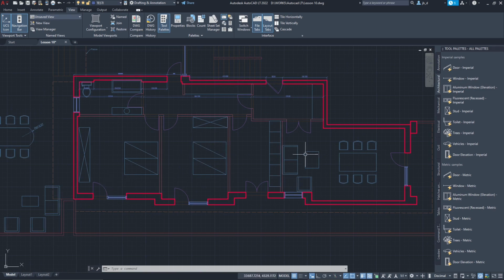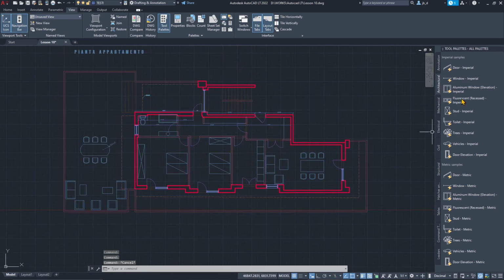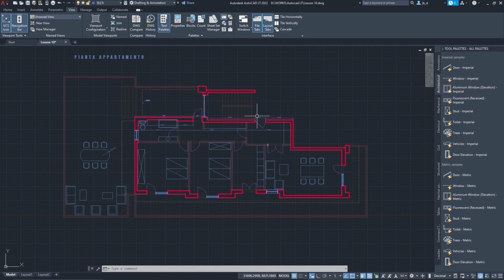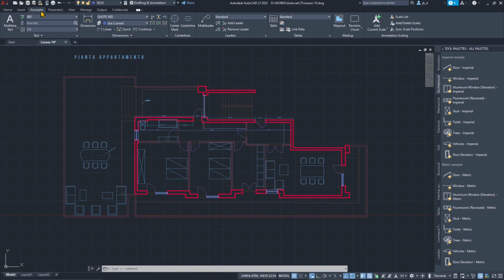So we created here, for example, blocks for the chair here and the armchair. These are all static. Now when they are dynamic, they are actually working with parameters. So we can call these parametric models or parametric drawings. It's a little bit different, and I'm going to explain to you this in just a minute. So we will first start by finishing the part concerning the blocks and talking about the dynamic blocks, and then we will move into the annotation.